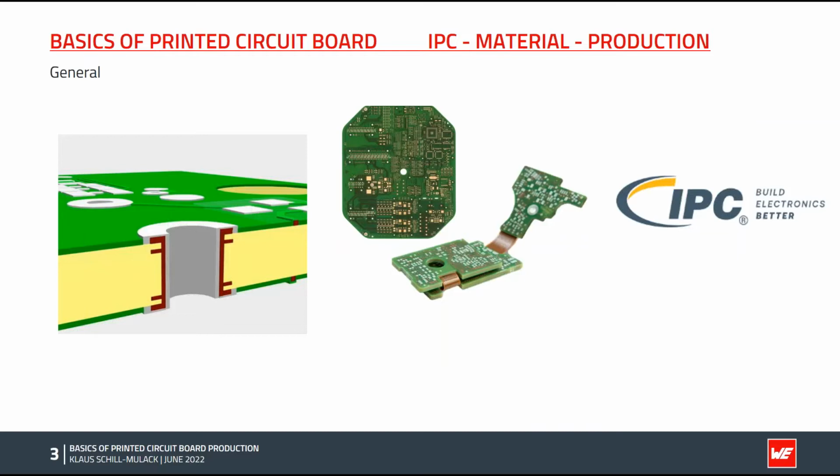The substrate for rigid printed circuit boards is, for example, FR2, which is phenolic paper, or FR4, which is glass fiber epoxy fabric. It could also be ceramic or aramid or other materials. FR4 refers to a class of flame retardant composites and is the standard material in printed circuit board technology. For flexible printed circuit boards, you will find mainly polyimide, but it could also be polyurethane and other materials. But the main material, of course, is polyimide.